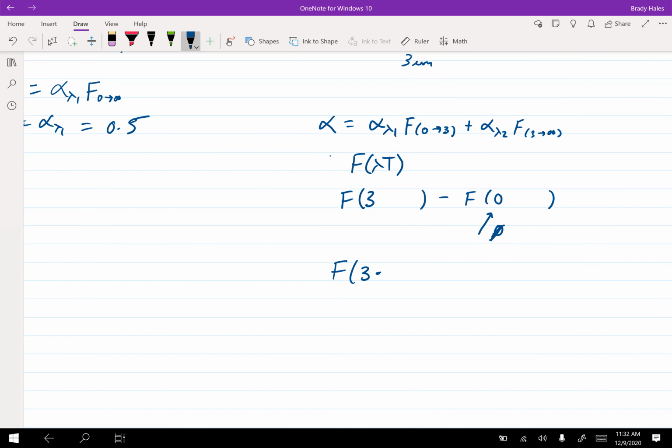Whenever you're finding alpha, you use the temperature of whatever is emitting and becoming incident on your system of interest. So this one would be 5,800 K, and that gives you a lookup value in the second column of Table 12.2.